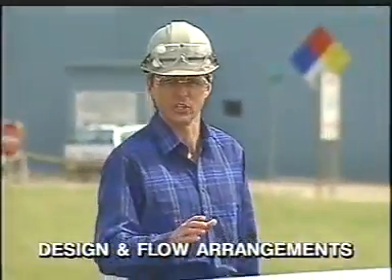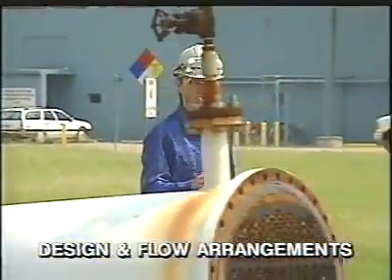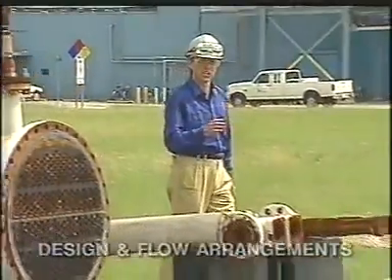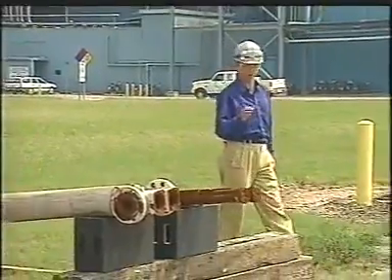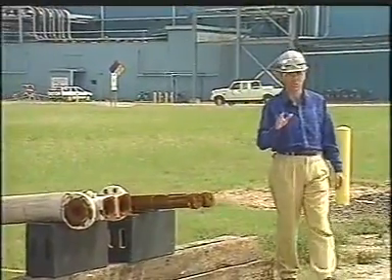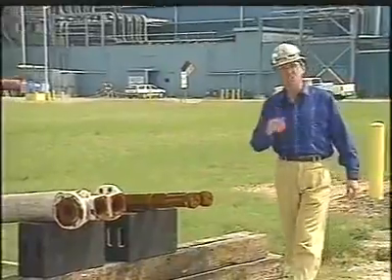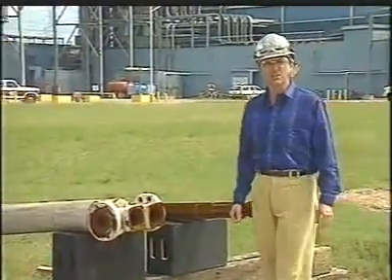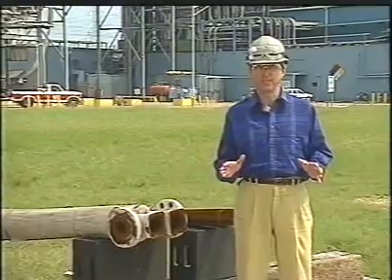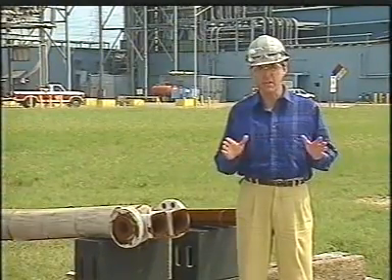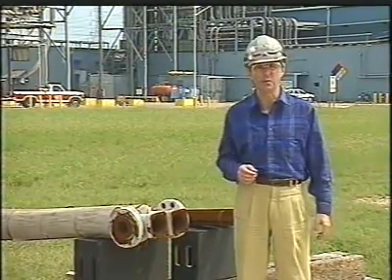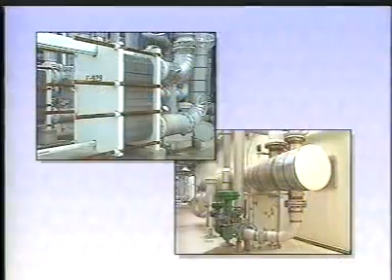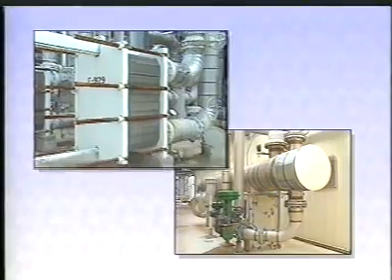In this section of the program, you will learn about heat exchanger design, including flow arrangements. Because tube heat exchangers are the most prevalent, the program addresses problems that arise when using tube heat exchangers and solutions to these problems. There are several designs for heat exchangers. In addition, these designs are varied as necessary depending upon the characteristics of the process fluid. In general, there are plate and tube heat exchangers. Each transfers heat from one fluid to another.